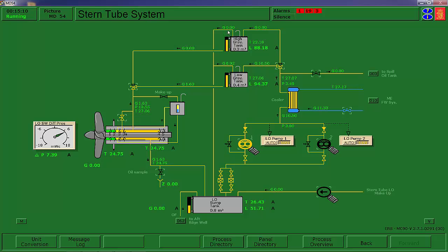So what they do is they provide 2 gravity tanks. We're on the lower gravity tank because the vessel is unloaded. And even so, they're giving you a lube oil to saltwater differential pressure. We're a little bit on the high side. But because we're so unloaded, we can't change that. That is set by the height of this tank. Now, once this vessel is fully loaded, let's say we're going up to Alyeska, we're loading crude.